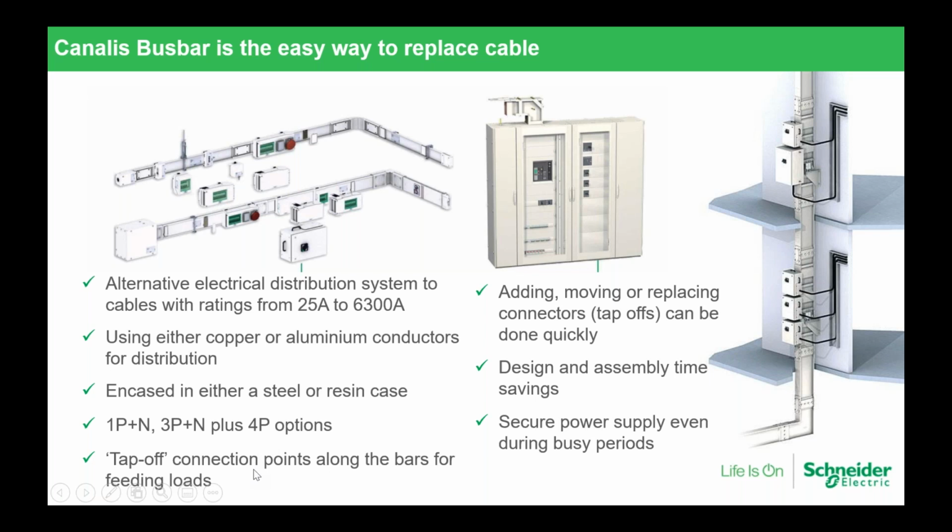We have a lot of tap-off possibilities. Tap-offs are the small enclosures you are seeing here that you can connect along the bus bar, giving you the opportunity to feed the loads and be sure you have the dedicated protective devices inside. With this tap-off unit, you have the flexibility to add, remove, or replace it every time.